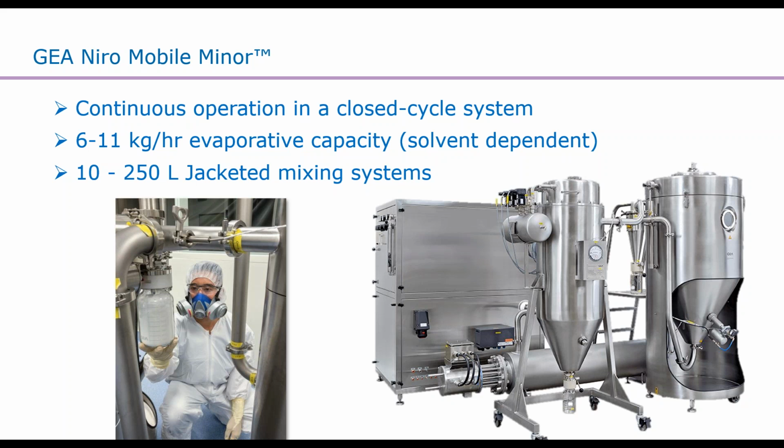It will depend on things like the solids content, the solution viscosity, the spray rate, and so on. But my rule of thumb is to spray for at least 30 minutes to allow the system to equilibrate. So if you assume 10% solids and 120 grams per minute as your feed rate, then you would need roughly 3.6 kilos of feed solution, which would generate 360 grams of SDD. You can then back calculate to determine the required amount of API based on the drug loading for your program.